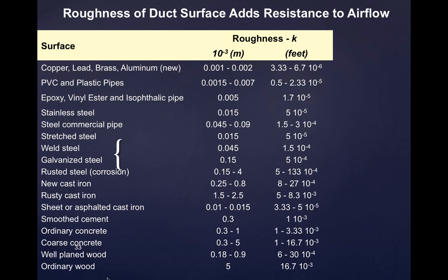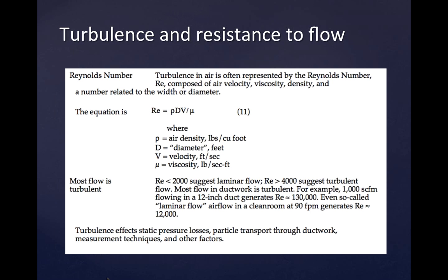You can calculate that using a formula, and generally, Reynolds numbers under 2,000 you consider laminar, basically uniform movement. Anything over 2,000, you start to say is turbulent. What we're dealing with is almost always over 2,000, so I wouldn't worry about it. If a question turns up on the exam, you may come across it.